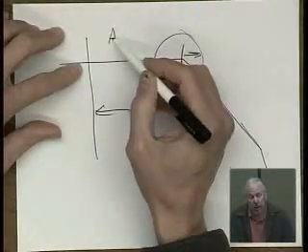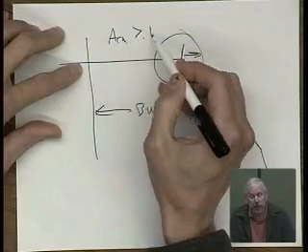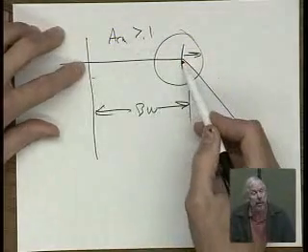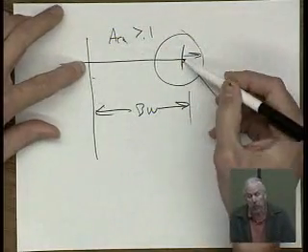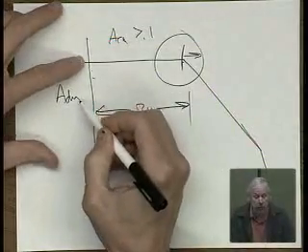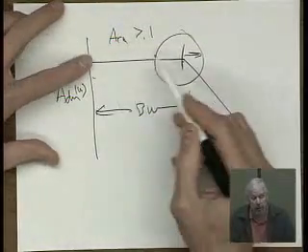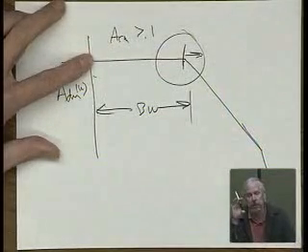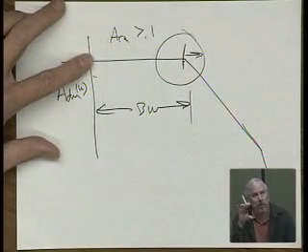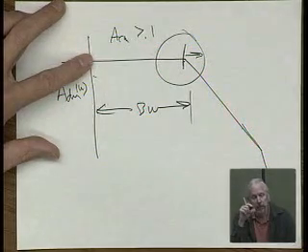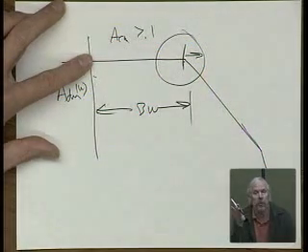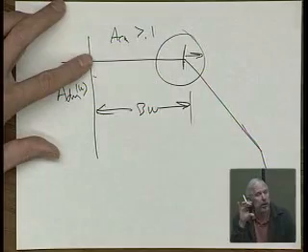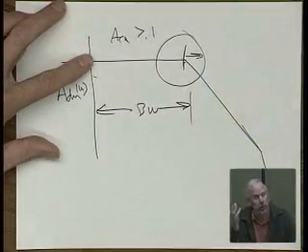We're asking that common mode gain has to meet that spec all over that bandwidth. So where the lowest frequency pole is, this is the differential mode gain as a function of frequency, right? But you have to check to make sure your common mode gain doesn't degrade, because I told you about the problem that the capacitance on the tail current source can degrade the output resistance of the tail current source, which can degrade your common mode gain, right?